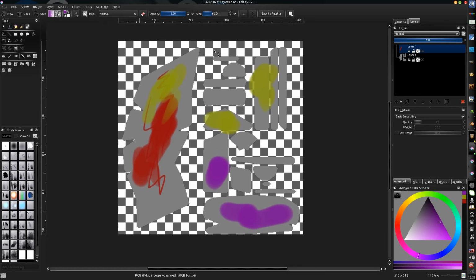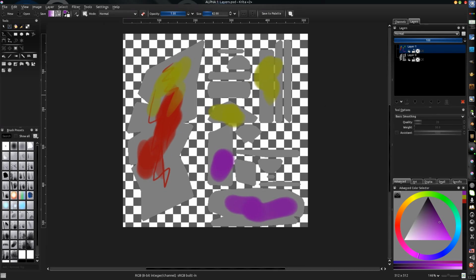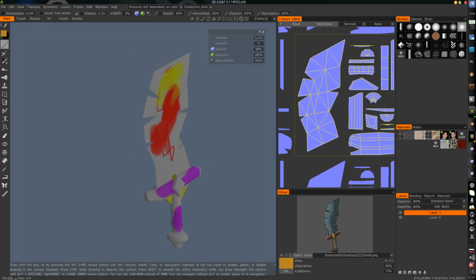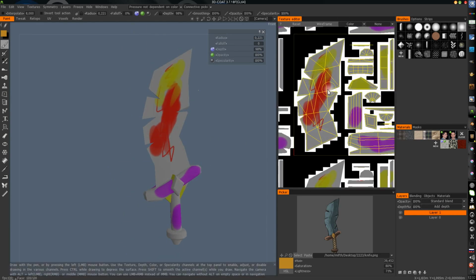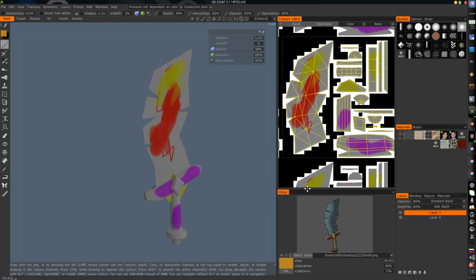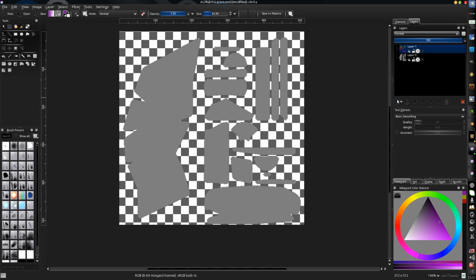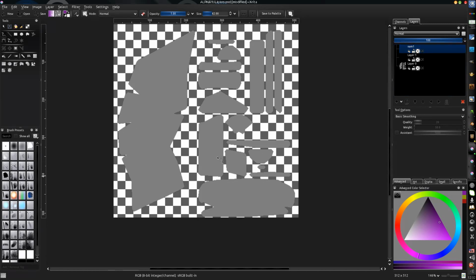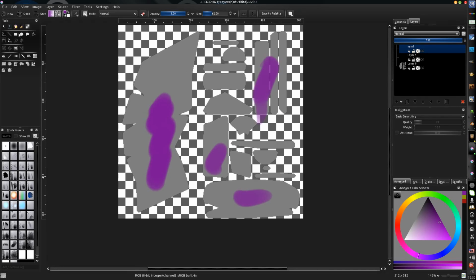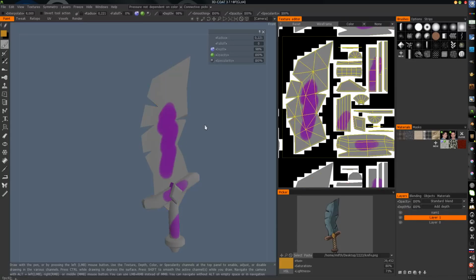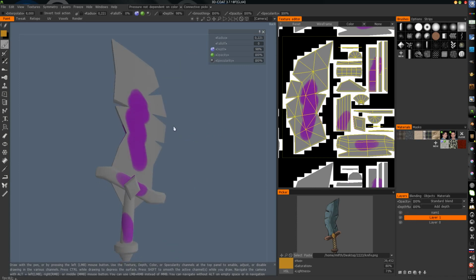It opens the PSD file as 3DCoat exports all to PSD. And we switch to 3DCoat and we see our updated image. Color, and we see here all the updated layers. You can switch it off, switch it on. So also we can add a new layer, but you need to make a new name. For example, name 1, and here do some stuff. Press save, and we see our updated layer.